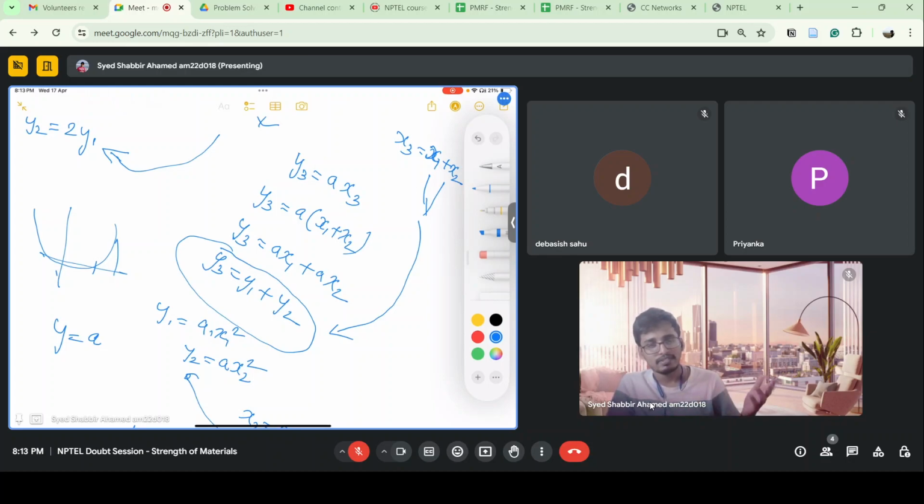Then we have gone to columns, stability of columns. We have seen how long and slender columns, when applied with compressive loads, will buckle, and instability happens, or they go into neutral equilibrium. So critical load, Euler buckling theory we have seen. We have seen how different end conditions give the effective length, and how they change my load carrying capacity. But it's just an introduction to the columns theory.